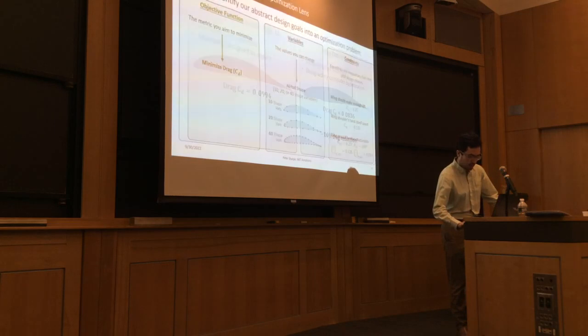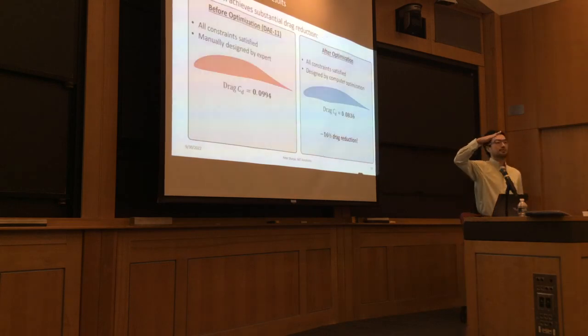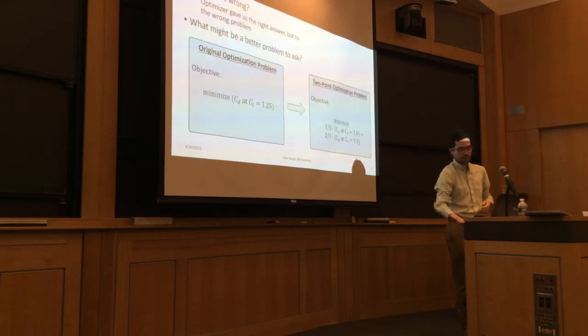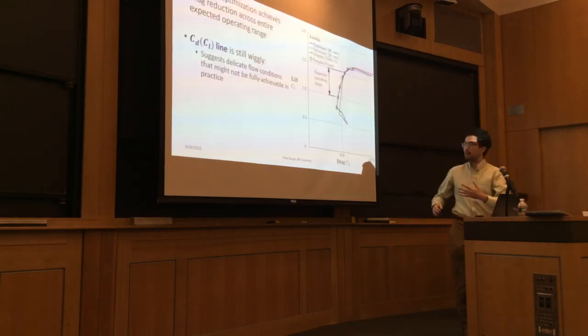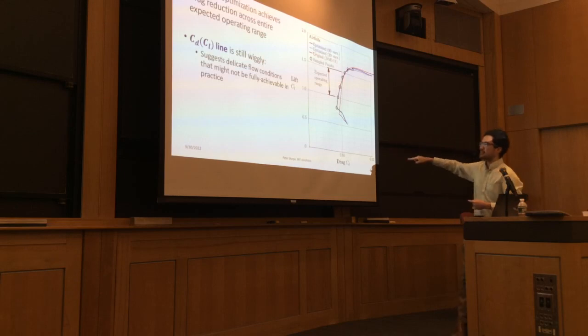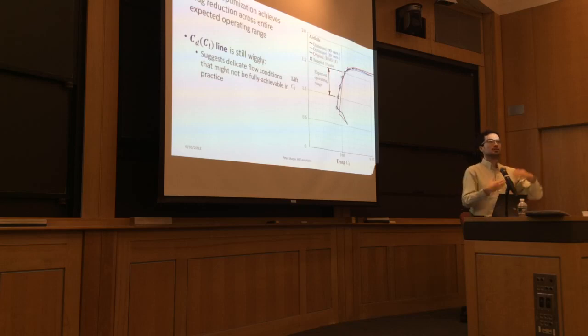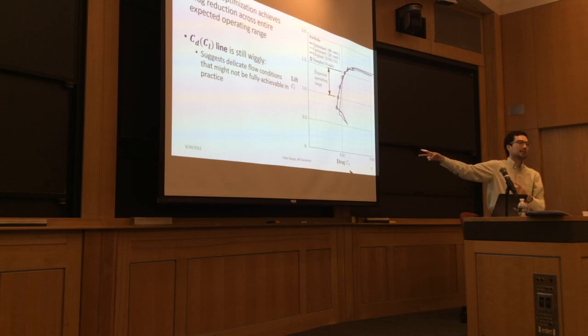It's a great question. Yeah, so they are a locus of different angles of the airfoil. So you start at 0 and you kind of tip it up. So normally the way that one might think about this is you plot that angle on the x-axis and the lift or the drag on the y-axis. But it turns out that the actual angle is a bit inconsequential because you can always just twist the wing to get it to the angle you want. So what we do is we sweep over that entire angle and then we plot the two things that we actually care about, which are the forces, because the angle itself is pretty easy to manipulate just by building it in.